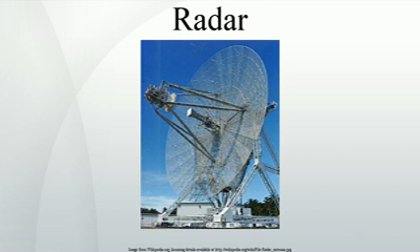Plot and track extraction. A track algorithm is a radar performance enhancement strategy. Tracking algorithms provide the ability to predict future position of multiple moving objects based on the history of the individual positions being reported by sensor systems. Historical information is accumulated and used to predict future position for use with air traffic control, threat estimation, combat system doctrine, gun aiming, and missile guidance. Position data is accumulated from radar sensors over the span of a few minutes.